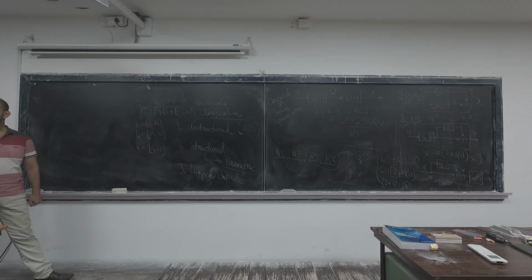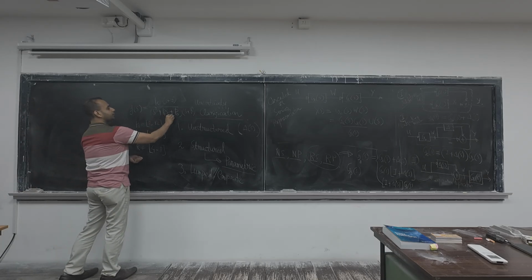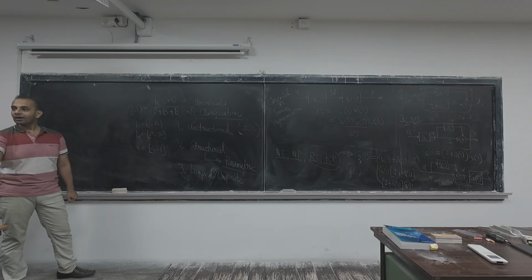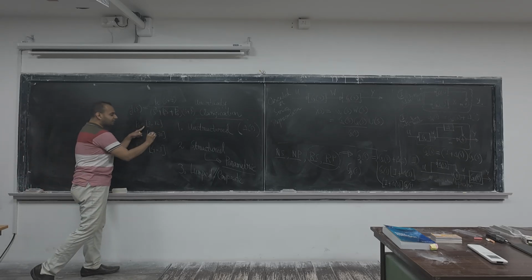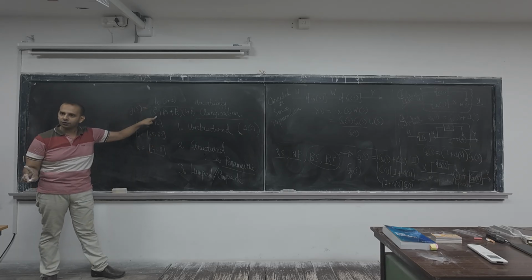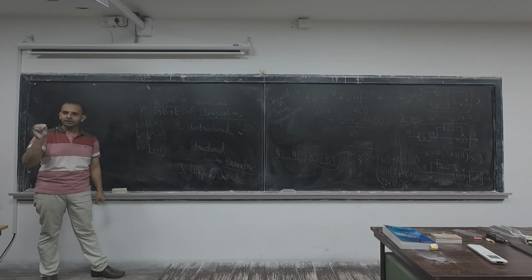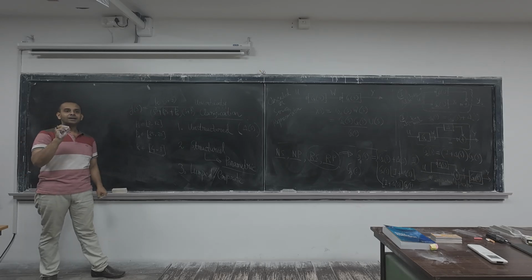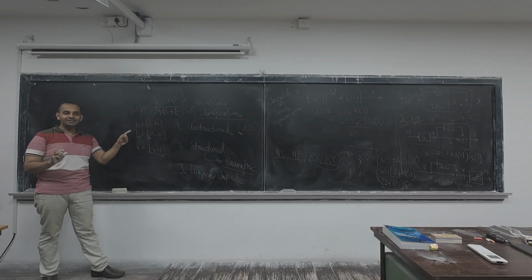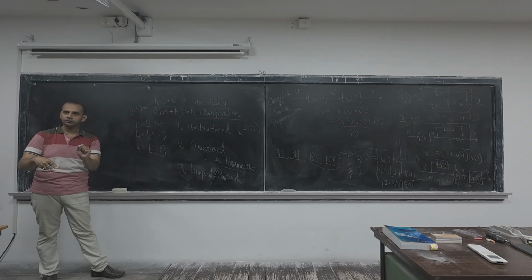Are you getting? As long as you have this k by s square plus p1s plus p0, then whatever may be the variation within this specified range, will there be any change in the structure of the transfer function? The poles will remain stable only. The poles can move a little bit here and there, right? The gain can be a little higher or lower, but is there any change in the structure? Structure of a transfer function means its poles and zeros.